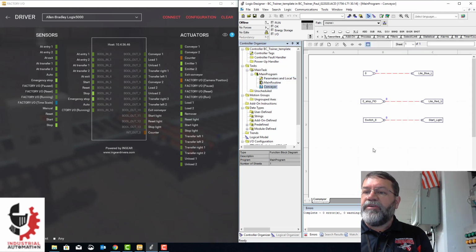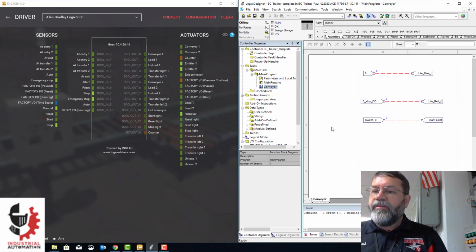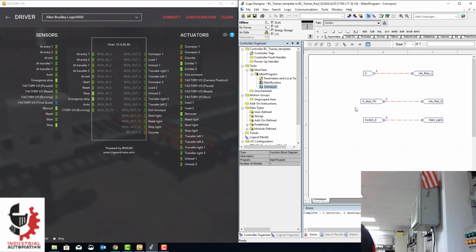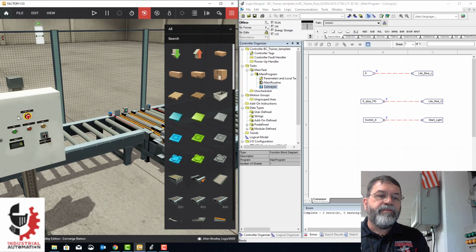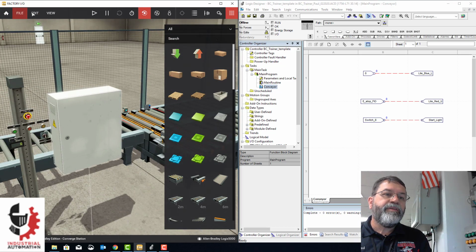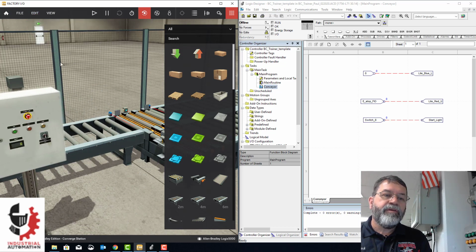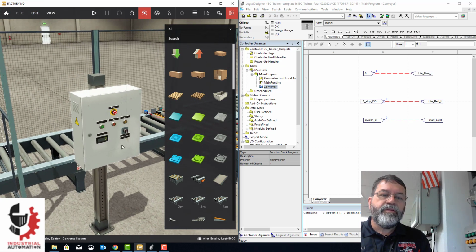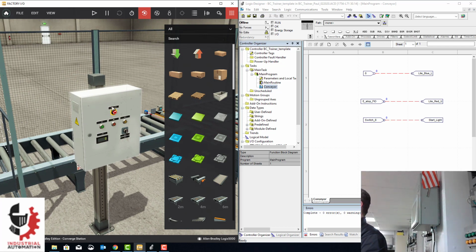So then if I go over to my code, I can put things in here that really mean something to me. Instead of having bool out 7, which I don't have any idea what that is, I've got an alias for eStop, and I call it eStop FIO. So FIO for Factory I/O for an abbreviation. That tells me that, oops, edit, undo. So that tells me that it's this eStop.